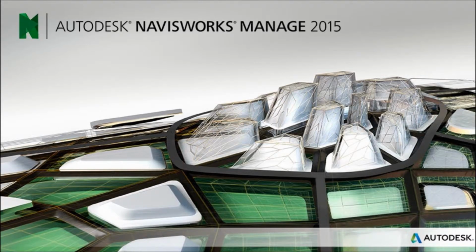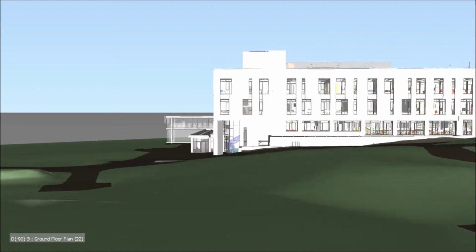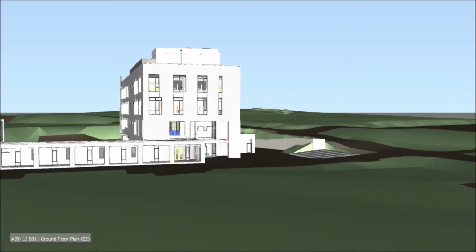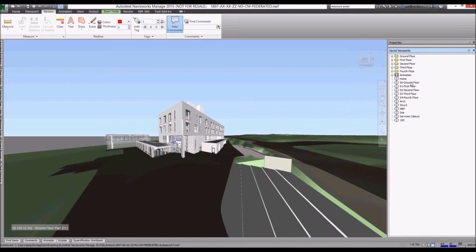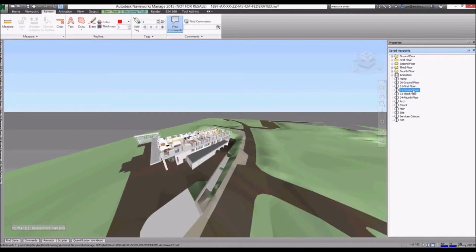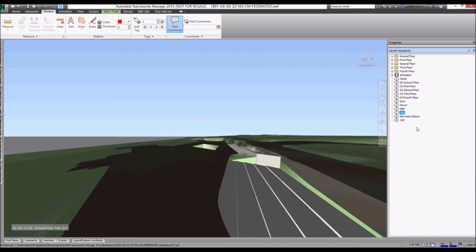We are also sharing a Navisworks NWD file, and although this can be viewed in a free version of the Navisworks software, Navisworks Freedom, we recommend the full version Navisworks Manage to get the most benefit from this. In addition to most of the uses possible in Design Review, Navisworks Manage provides the additional ability to use clash detection tools, to add the timeline to the project and simulate the construction sequence, and quantification tools to measure and take off elements in the model.